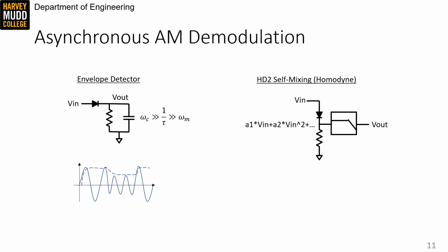An example of an envelope detector operating on an amplitude modulated signal appears below the circuit. The dashed line is the output of the envelope detector, and you can see that it tracks the height of the amplitude modulated signal, but that there's a time constant when it is decreasing, because the increase in our envelope detector is governed by the very fast diode response, but the decrease is controlled by the discharge of the RC circuit.